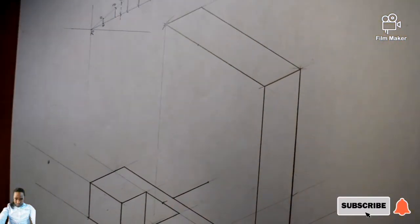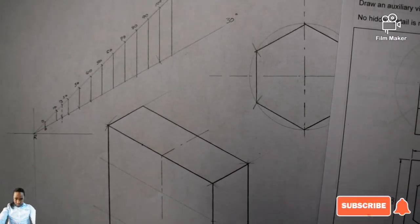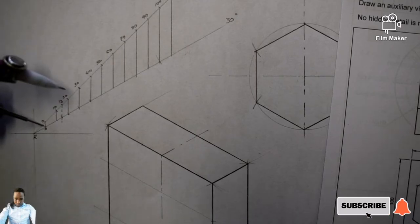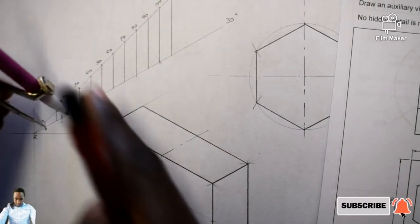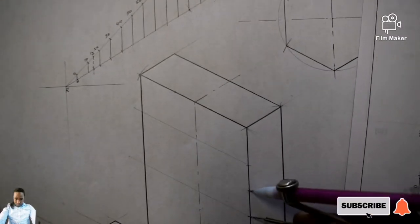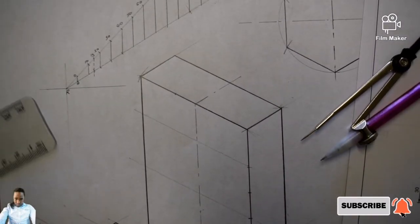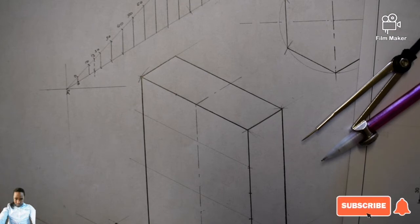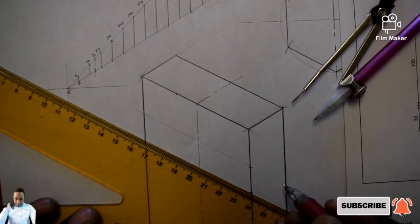Then from there I can take my 30 millimeter ruler, this one. Okay, so the 20 millimeter converted to a scale, I'll place it at my point 0 along the line of 45 degrees. Where's my 20? This is it. Then I come to my drawing, place it here, and I mark. See, that is correct. So it's the horizontal center line that is at an angle of 30 degrees anti-clockwise.